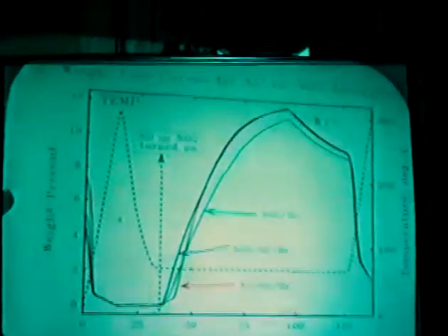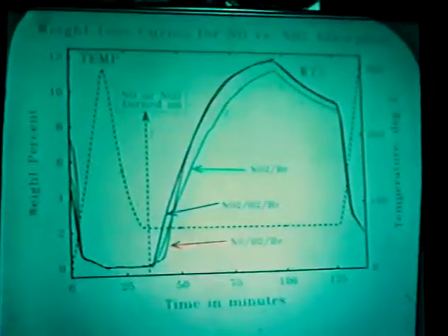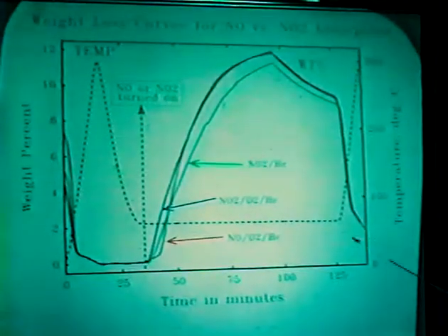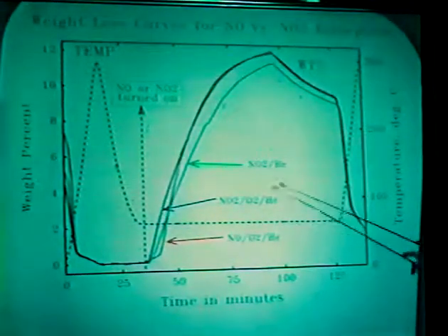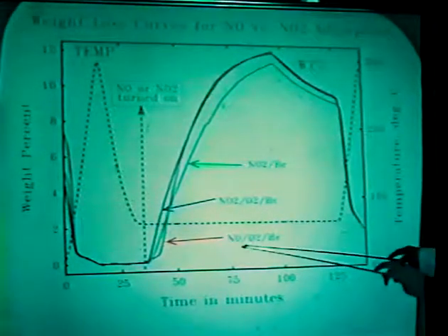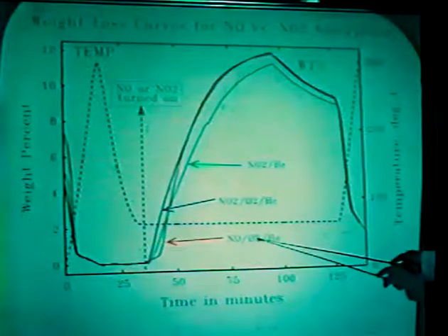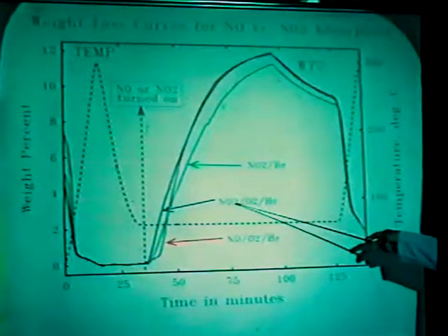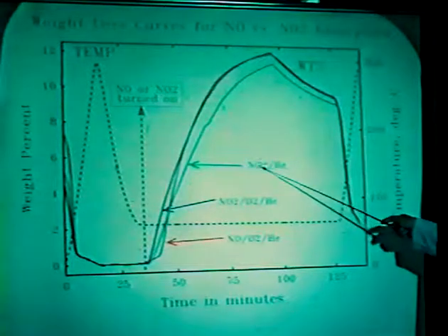Now to look at the differences in the rates of adsorption between NO and NO2. For this series of experiments, we did 3 experiments eliminating CO2 from the combustion flue gas. We were fairly confident at this stage that CO2 does not either interfere or participate in the reaction. And it simplifies the mass spectrum by eliminating it from the experiment. And so we did 3 very comparable experiments where we looked at the adsorption of NO in oxygen, balanced helium, NO2, O2 and helium, and NO2 and helium.